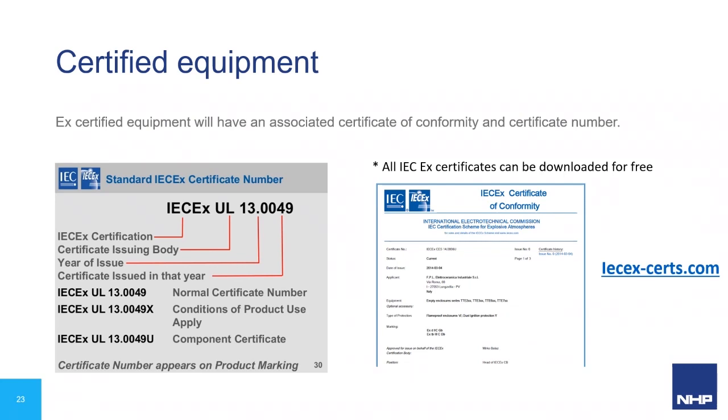Following that, you have what's printed UL in this case, which is the certificate issuing body or the test house. Now there are other test bodies like TUV, IMQ, there's a number of them, but effectively they're just a test house that issue the certificate. After that, you have the year of issue, which is 13. So in this case, it is for 2013. And then you have the job number, which in this case is 0049. So this is saying this is the 49th certificate that has been issued within 2013 by the test house UL.